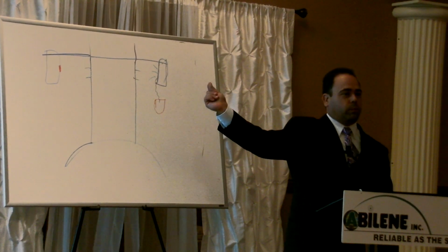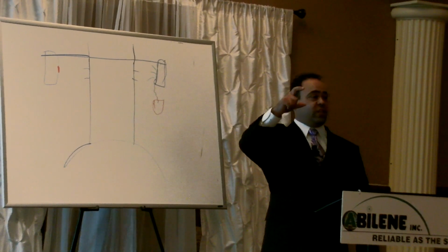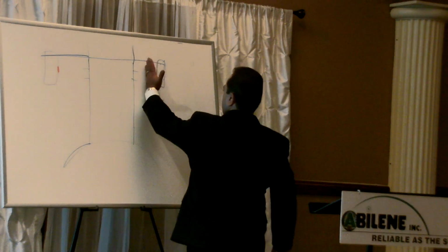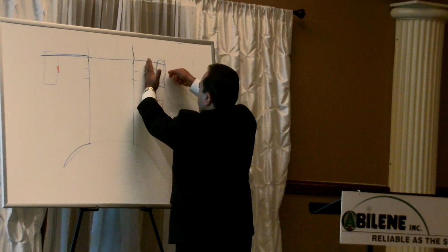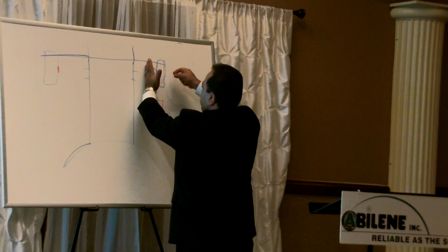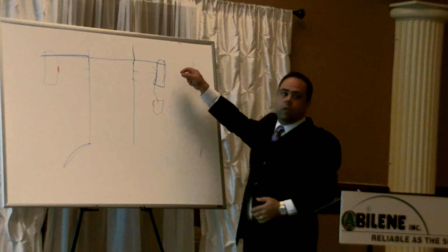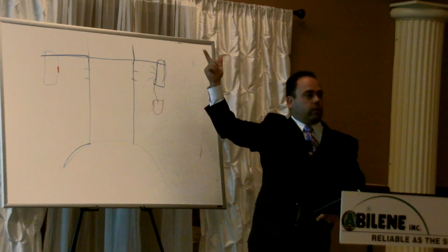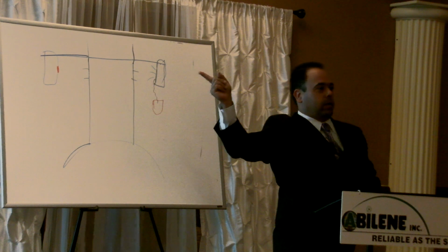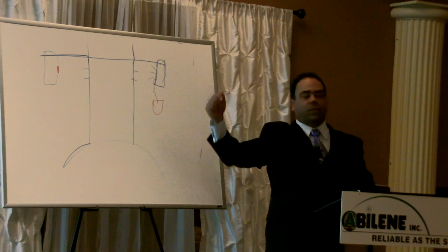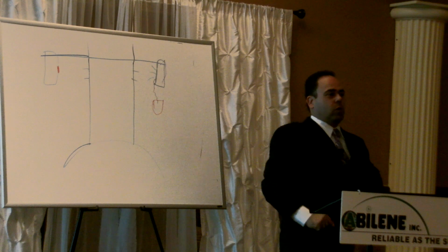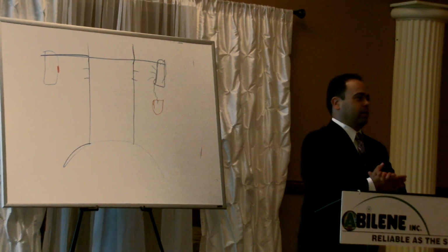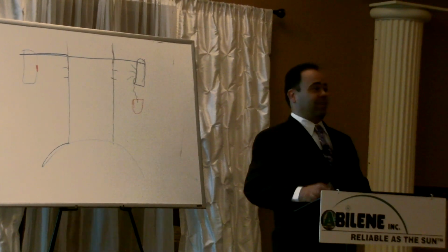smoked plexiglass, right? You might not see it, but it does have a tint to it. You take the paper off, you put it in front of the lens, and then you set the dial down till it rings. When you remove the lens, the light should go out. And then I want you to just move it a quarter turn back brighter. Quarter turn brighter, okay? So when the inspector comes in and says, you didn't properly calibrate the smoke alarm, he sees that paper on there, he knows why. And you can't debate it, all right?